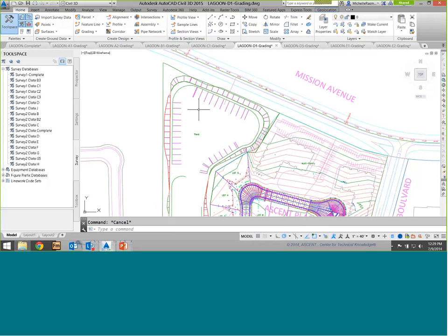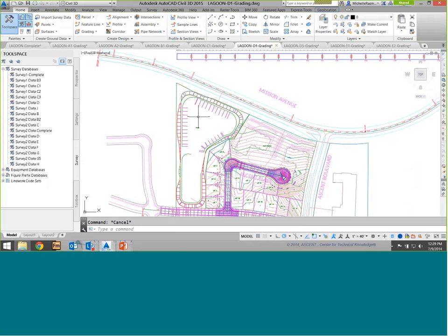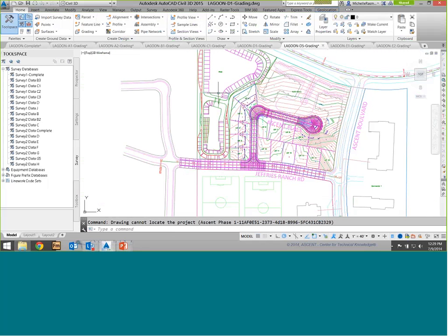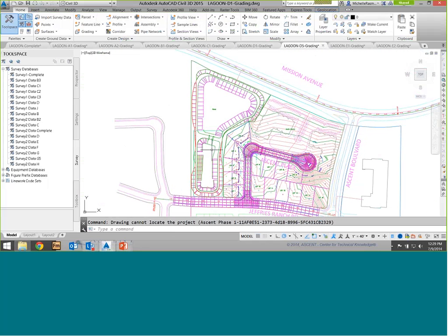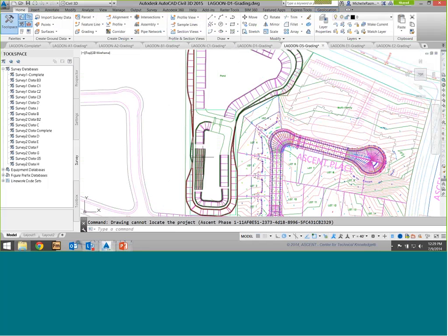I'm going to go ahead and jump over. You've seen how to add a baseline now. You've seen how to add a region. I'm going to jump over to one that has all my baselines and regions assigned. So you can see I've gone in and I have my bench region here, a certain slope region, another slope. This is, I think, the 33% slope, and this one is a 45%, so that it creates all these transitions that I need. But I've left this area in the middle open.